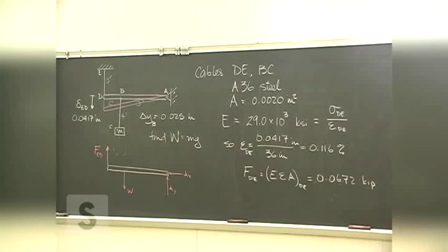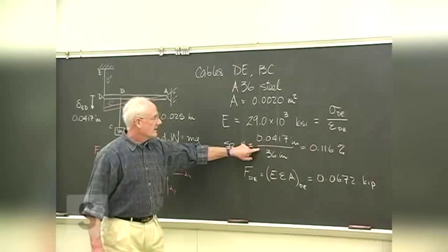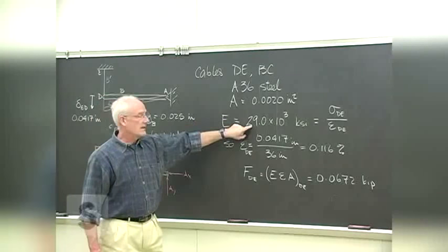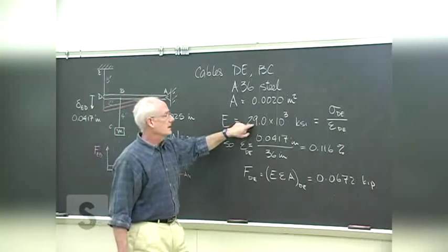Joe, okay? Where do I go from here? Yeah, you got that. Now, with the original length, which you didn't write down, it's 3 feet. Now you can find the strain in that piece. Once you find the strain, you can use the modulus of elasticity of that material, which is a given material property.